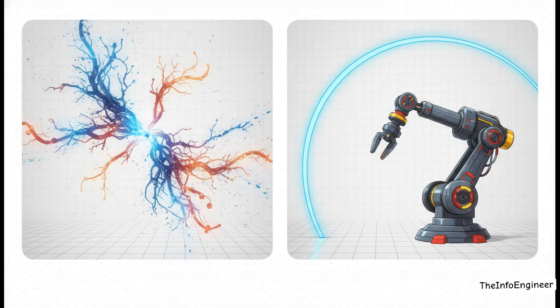AI is heuristic, meaning it guesses, it tries things, it operates based on probability. Factory robots, however, are strictly deterministic, meaning they follow a rigid, set mathematical path. The robotic arm is just executing those inverse kinematics and PID loops we just talked about. It does exactly what the math dictates, with absolute zero room for guesswork.